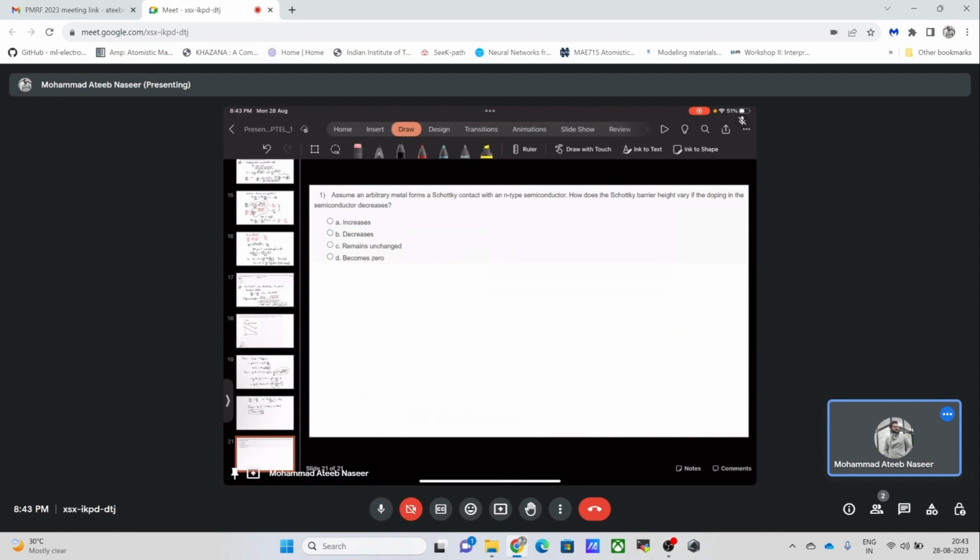So this chi s was fixed for a particular semiconductor. However, for a metal, we had drawn something like this. If this is the vacuum level, then this will be the Fermi level for the metal. This will be the metal work function, and this is fixed.